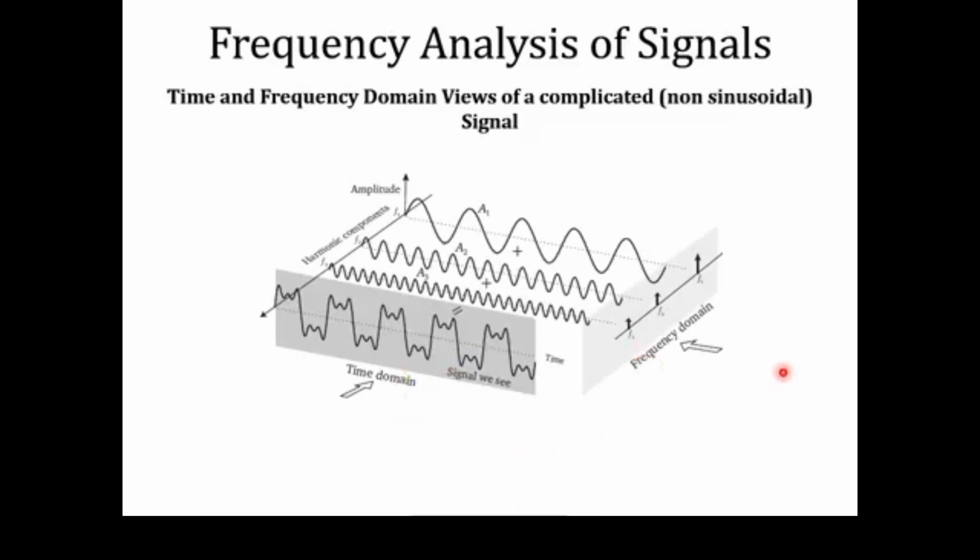If we look at these sinusoidal signals in the frequency domain, our point of view should be in this direction because we want to observe with respect to this axis. So how will these sinusoidal signals look? You can simply imagine a whole sinusoidal signal will be covered by a single vertical line, or the whole variation pattern of a sinusoidal signal will be covered behind this single vertical line, which is so called a spike.